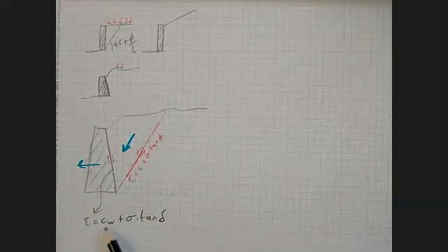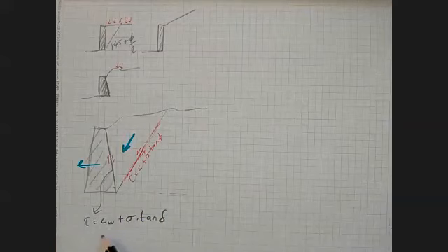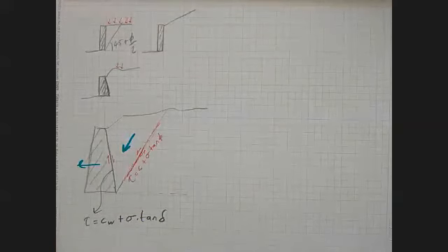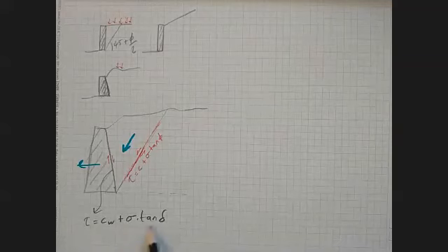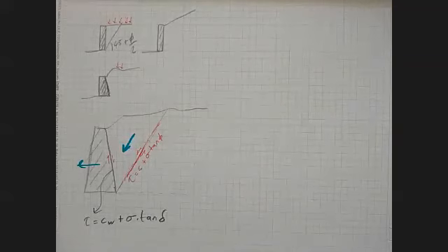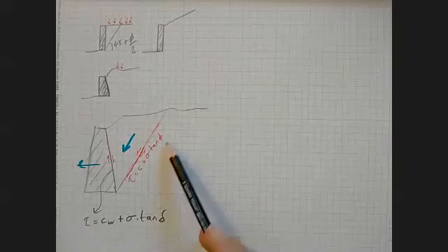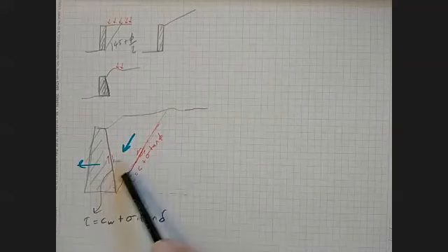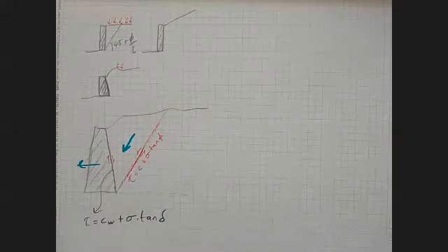I didn't want to call it A because we had A in the modified strength envelope, plus normal stress times tangent delta, where delta is another friction angle, not the internal friction angle of the soil, but the friction angle between the wall and the soil. Okay, so now we are able to define everything.